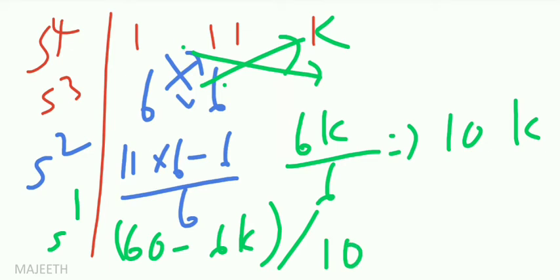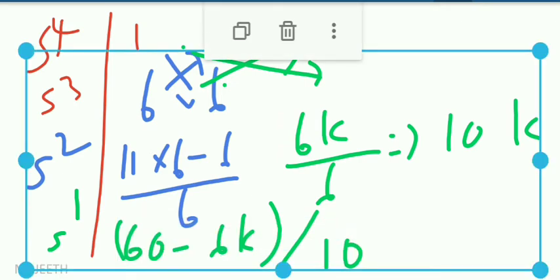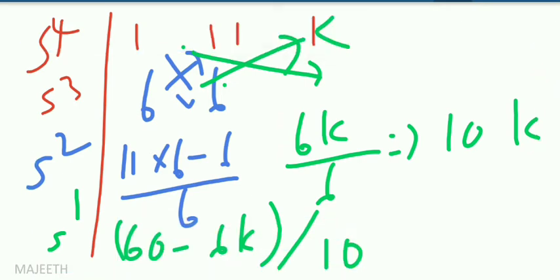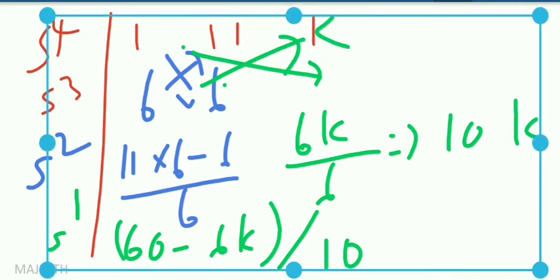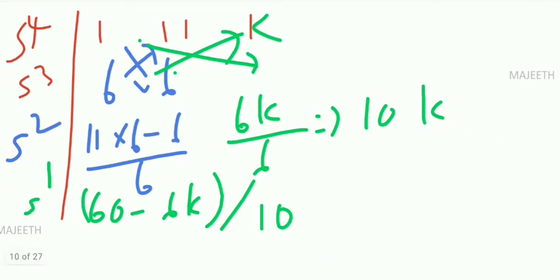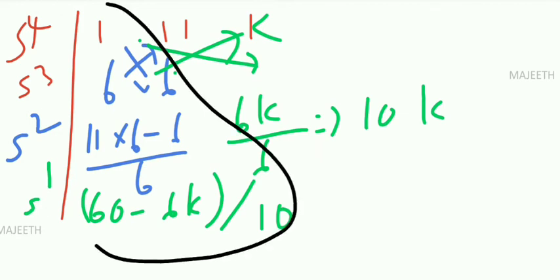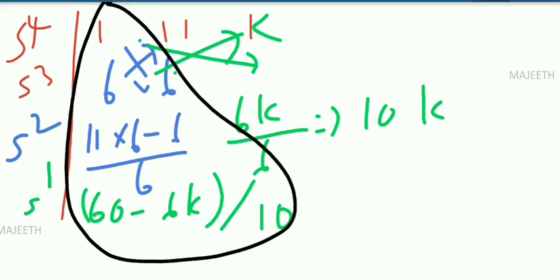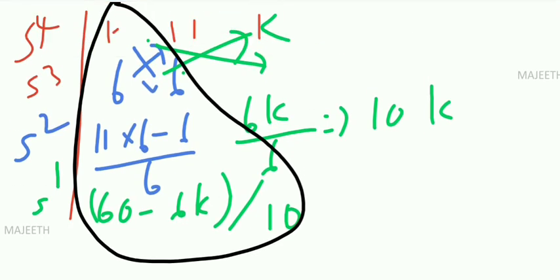This is the first column, right? Otherwise I write again. Okay, so what we do? So first column should be positive for a stable system, right? So this is my first column. This column should be positive for a stable system, right? So where is k? We are having the one element. This is positive, no problem. This is also positive, this is also positive, but this must be positive.